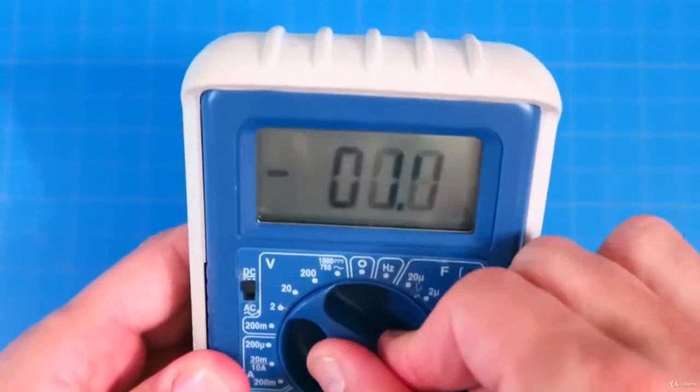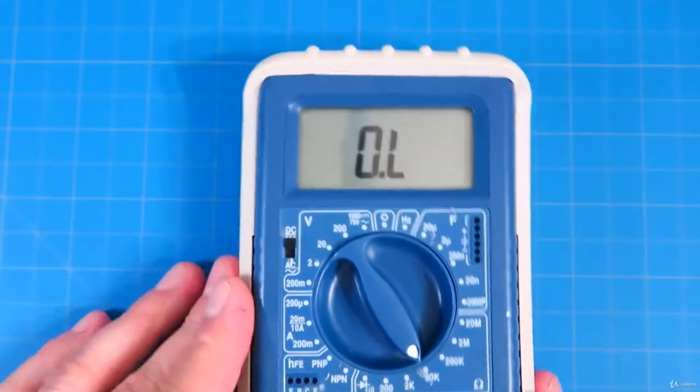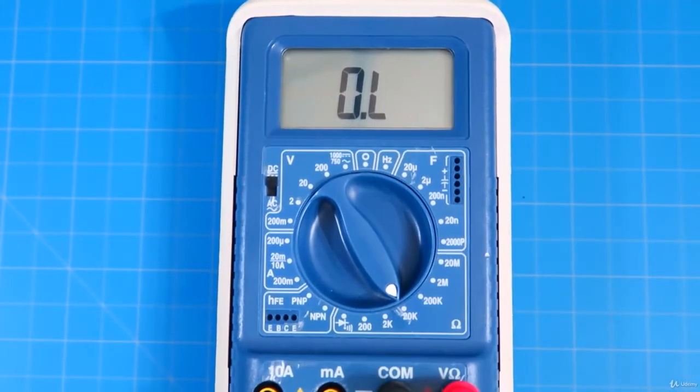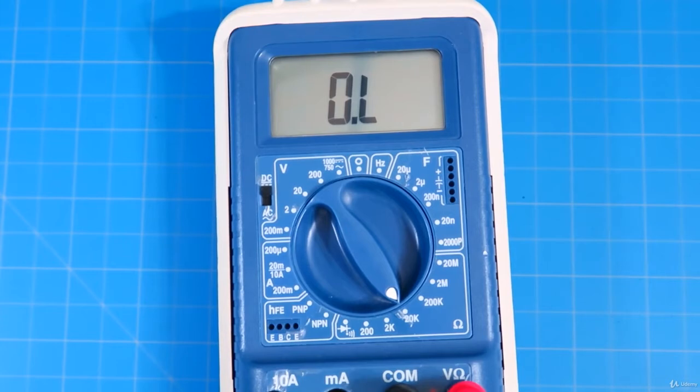Okay, all right. So now what I'm going to do is I'm going to close up the surface mount components, and we'll put our meter over here, and we're going to kind of go back and forth. So we're going to set our meter, so it's 4.7K is the value, so we'll put it on 20 kilo ohms range. And again, we really don't know what an ohm is and all that, but just bear with me. All right, so we've got that, so we got our meter, and now we're going to come over here.